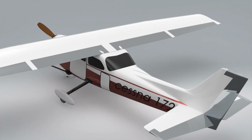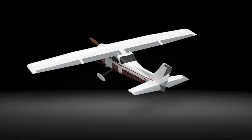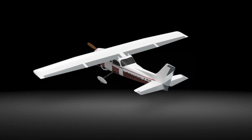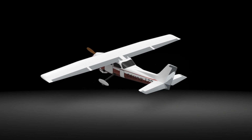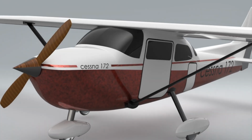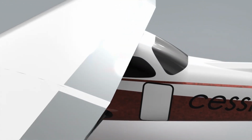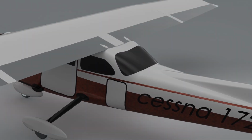Likewise, if we push the yoke forwards, we lower the elevator, causing more airflow to bend around the airfoil, creating more lift at the rear of the plane. This creates a moment which acts to pitch the nose of the aircraft down, as there's a greater force pushing at the back of the airplane about the aircraft's center of gravity.